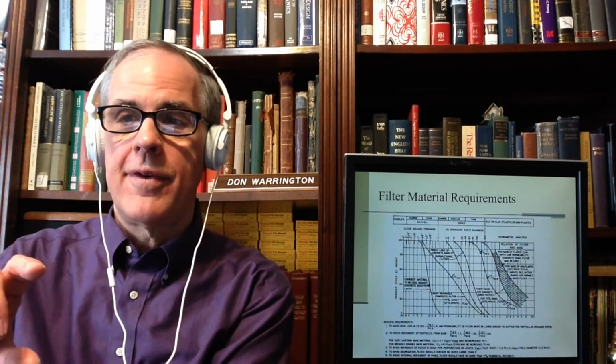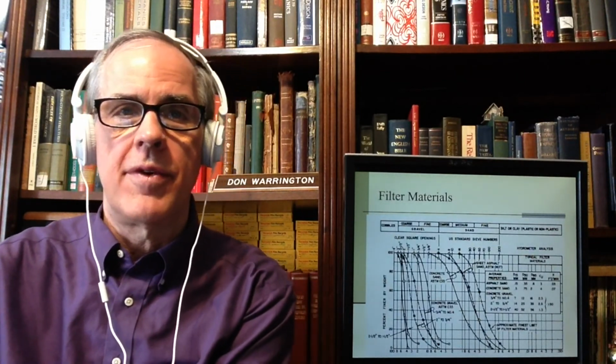These are how to use filter materials. Today we have geotextiles to do this work for us, and we can use those either by themselves in some applications, or in some applications we might want to have a combination of both. Have, say, gravel, then some kind of sand, then a geotextile, to really keep our filtration proper, to allow water to flow through and not the fine particles of the cohesive soil. But filter materials are traditionally the way we've dealt with this. But now with geotextiles, we have another weapon in our arsenal to solve this problem.